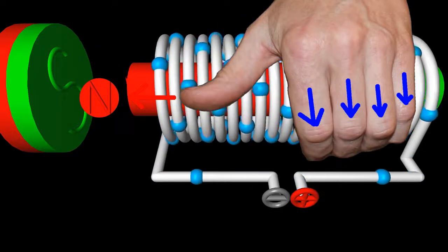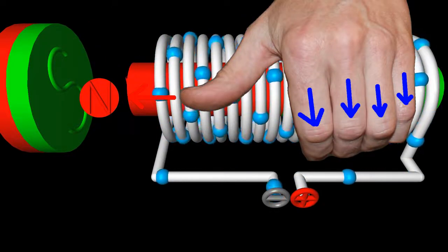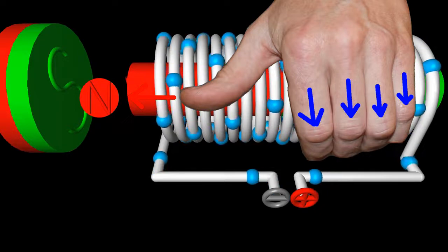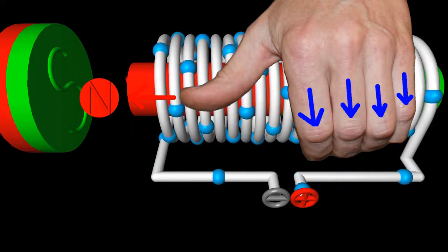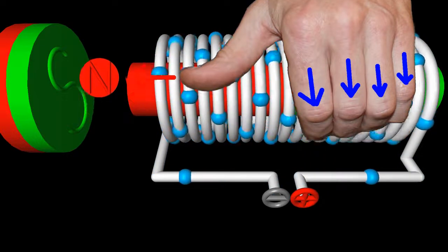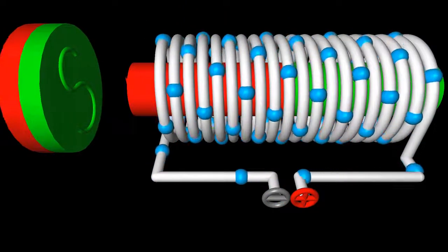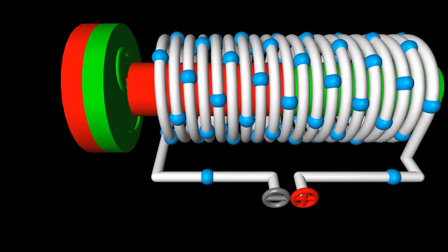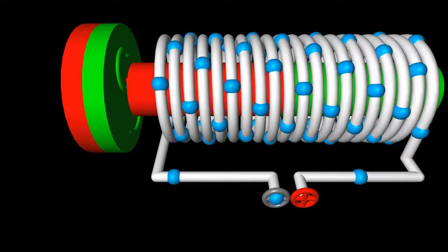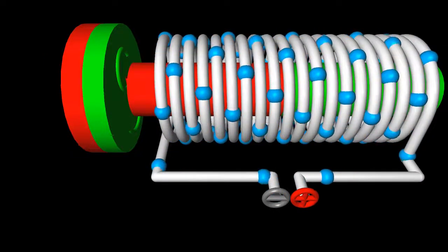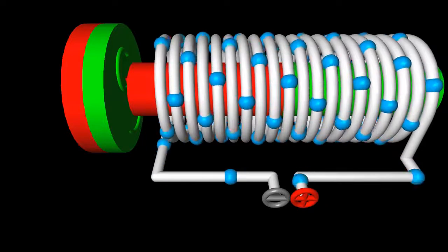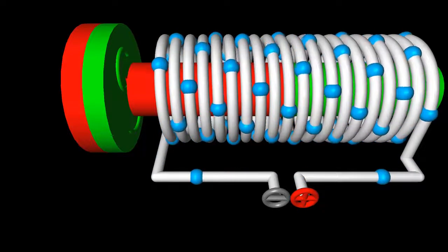Now you have to wrap your left hand around the solenoid with the fingers pointing into the oncoming direction of electron movement to find the magnetic north pole. Once again, that pole is on the left end of the solenoid, and so there is an attracting force between permanent and electromagnet. As mentioned before, the polarity of the voltage source has not been changed.